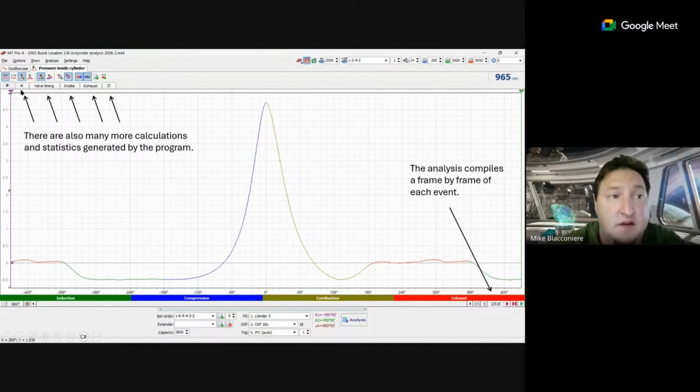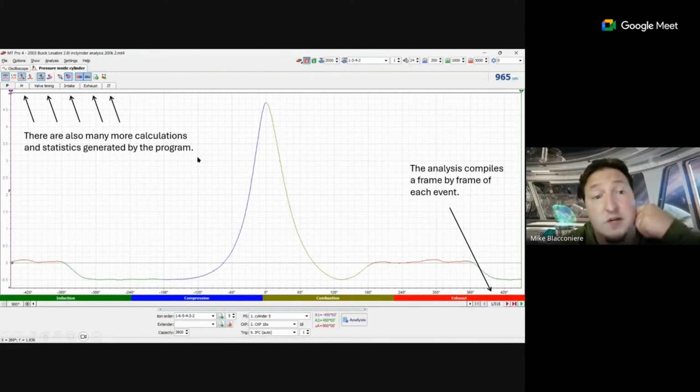So the data is, you have cylinder air mass that it'll calculate. You have valve timing. It'll show you your exhaust valve closing and your intake valve opening under valve timing, in a really neat timing chart. The intake manifold pressure calculation, and then your exhaust pressure calculation. So the exhaust pressure is really nice if you're suspecting a plugged exhaust. You could do this test, look at this tab, and then decide if you're creating too much pressure in the exhaust.